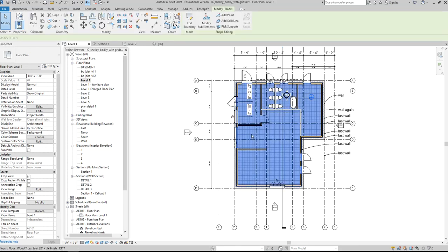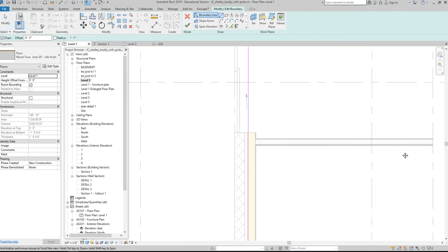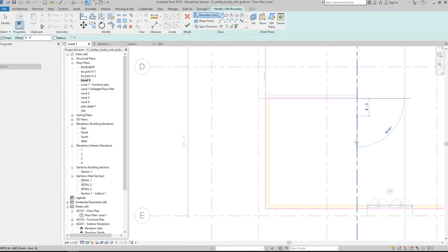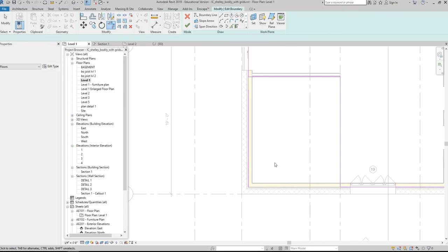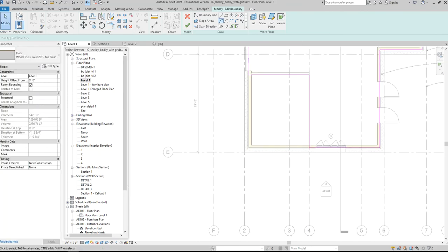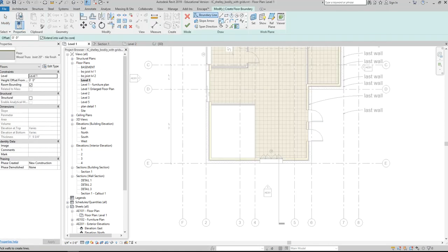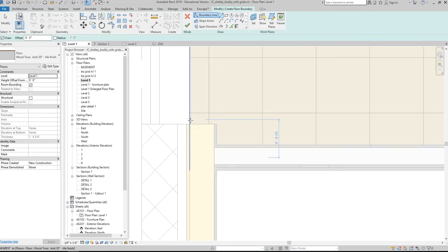But what I think you were saying was, well, I'll just take my boundary and cut a chunk out of the main floor, right? And then you'll replace that, trim, replace that with a floor with a different finish, right? So I'm gonna hit finish there, and then I would create another floor right there, right? So that's maybe what you were saying. Okay, so I'd click on floor, I'd hit architectural floor, and I would outline my floor again, starting where I sort of cut it off.